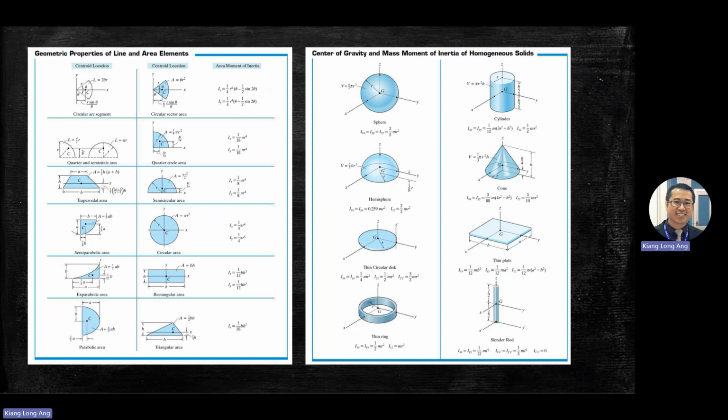For the second object, the disc, you're referring from A to the center of gravity 2 here. This is your D2. So there's a D2 here. Plus md square, so the d is d2 square. Understand? So that is the difference when you change the reference point to somewhere else.